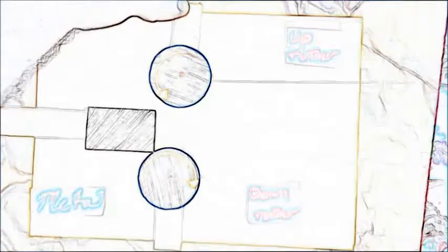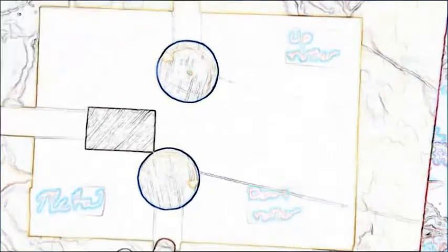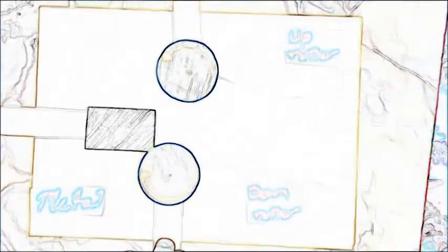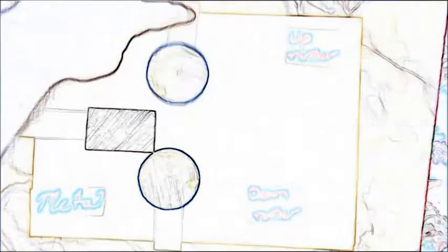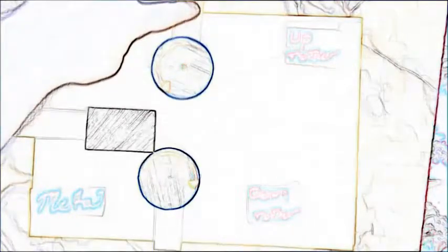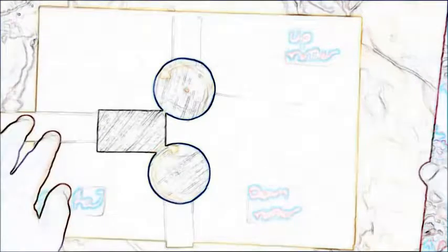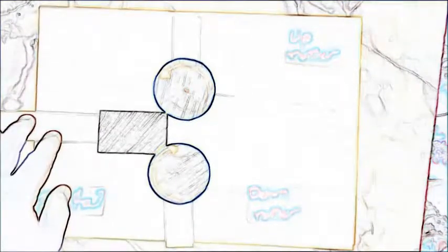In a rolling process, it is necessary to have a metal plate, an upper roller, and a lower roller. The rollers move in opposite directions to each other. One moves in the clockwise direction while the other moves in a counterclockwise direction. The upper roller can be adjusted according to the size of the metal plate. It can be moved up or down according to the metal plate.